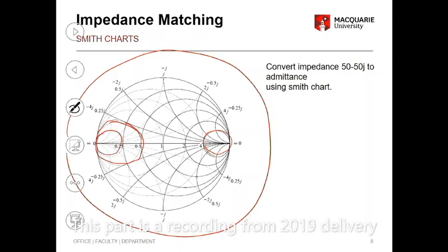Right? So if you have an impedance, you have R plus jX, right? This is called resistance, reactance. Then you have admittance, you have conductance, and then susceptance, right? This is called conductance, this is called susceptance. I don't know how to spell it actually. Susceptance. So somehow you have G plus jB. Now the G is called the constant conductance circles.